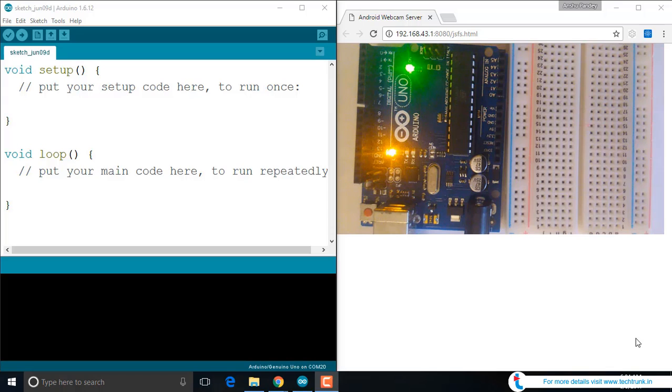As we know, the PWM channel is available on 6 pins in Arduino, that is pin number 3, 5, 6, 9, 10 and 11. But the onboard LED that we have is on pin number 13, so we cannot use the onboard LED to control the brightness, unless we short pin number 11 and pin number 13 together. Or otherwise, we can connect a separate LED on pin number 11 as well. So we'll be trying both ways.